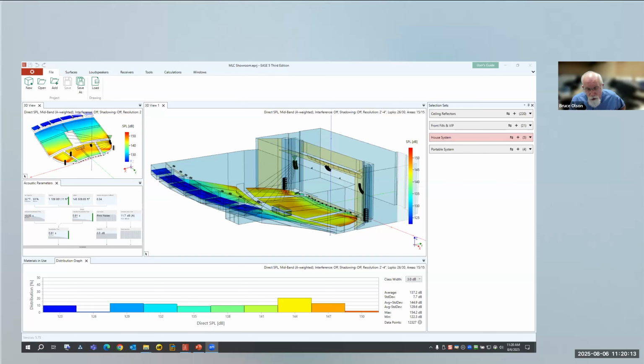So what you want to do is, in the AutoCAD model, you should set the base point to be where you want to have the origin for X and Y in the EASE model. If you don't have access to AutoCAD to be able to do that, most people who have Revit also have AutoCAD. Then in Revit, that's setting the project reference point, and there are ways to do that for that specific export by resetting the project origin to where you want it in the model. Hope that answers your question, Brian.